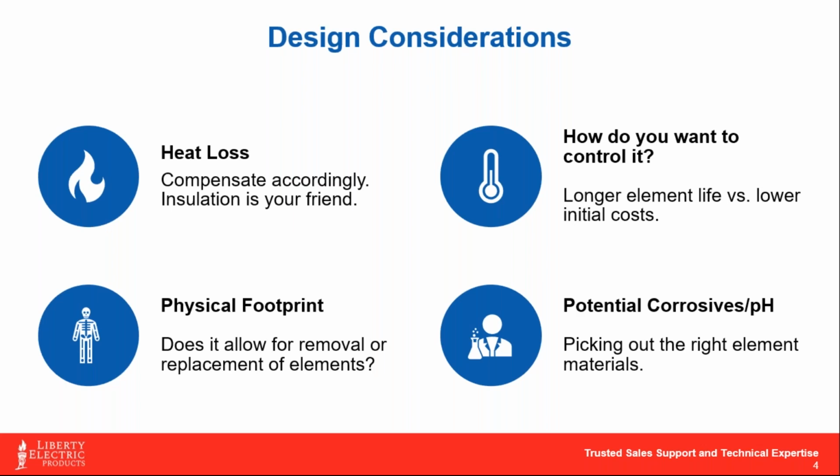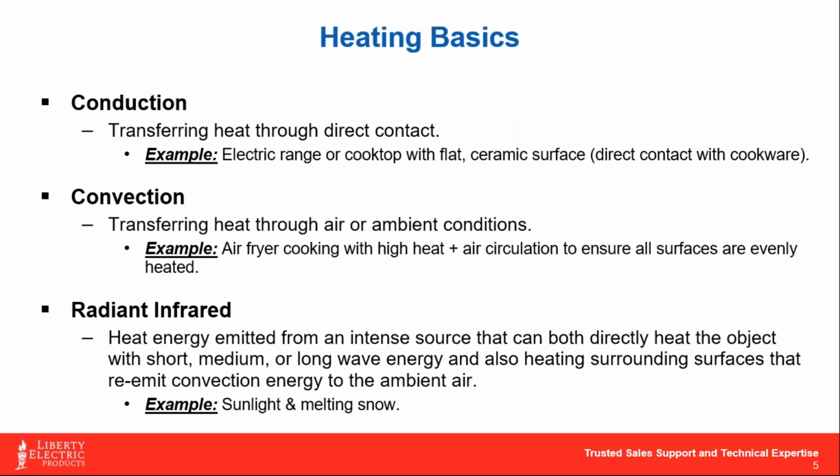How do we want to control it? There are several control options, where I don't need something fancy for this application, versus I want precise temperature control and better longevity out of my elements. And then, of course, what is the heating element going to be subjected to? Are there corrosives or issues with caustics or acids, where we have to worry about what type of sheath material we're going to use for the heater itself to come in direct contact with.